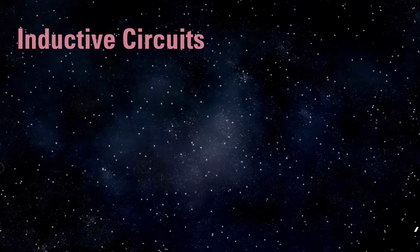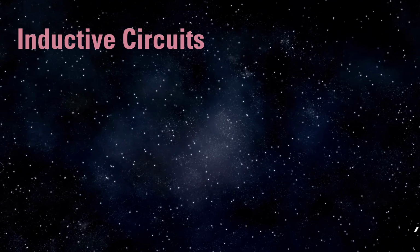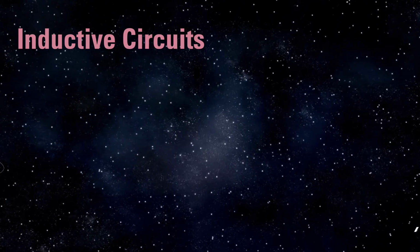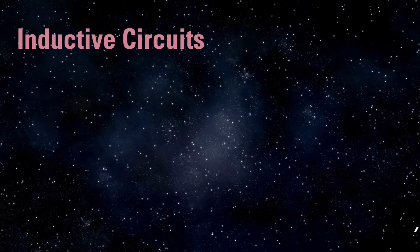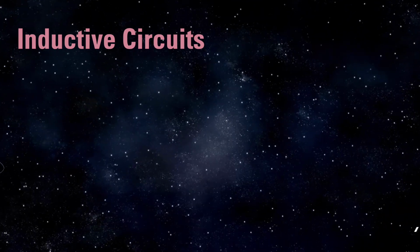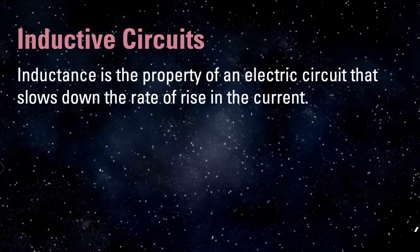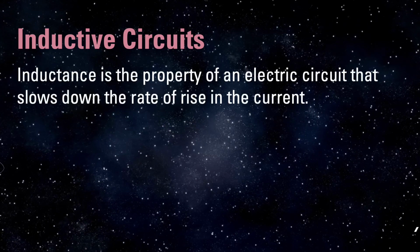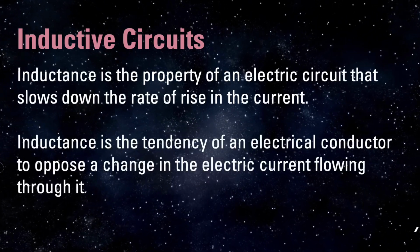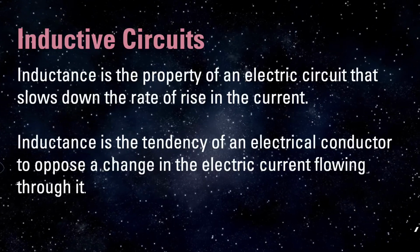A pure inductive circuit is a type of circuit in which the only quantity in the circuit is inductance, with no other components such as resistance or capacitance. The current in this type of circuit lags behind the voltage by 90 degrees. Inductance is a property of an electric circuit that slows down the rate of rise in the current. Inductance is a tendency of an electrical conductor to oppose a change in the current flowing through it.